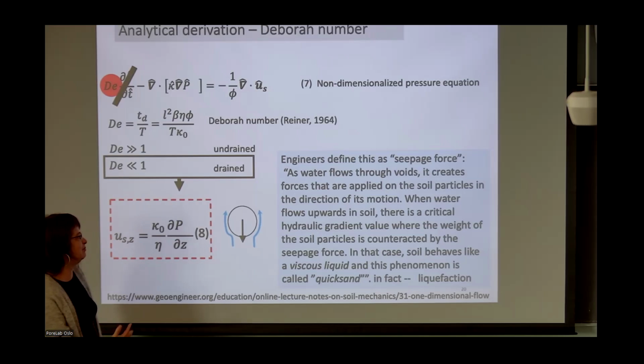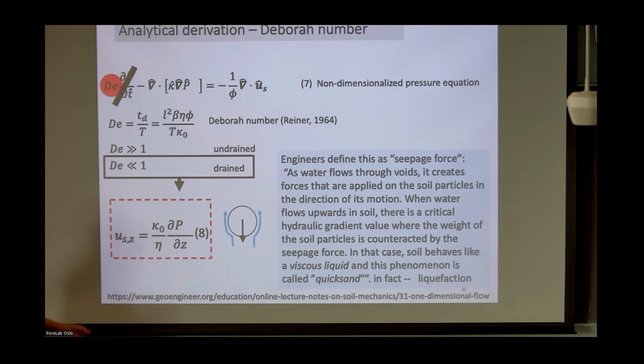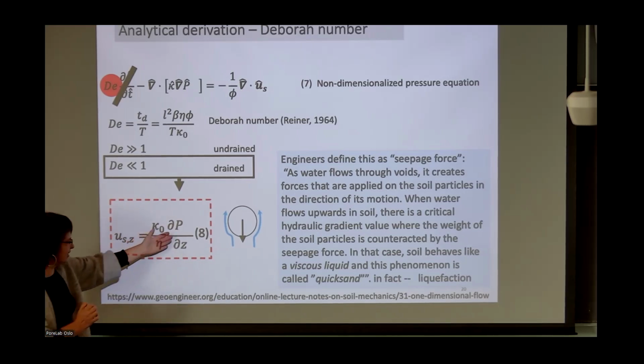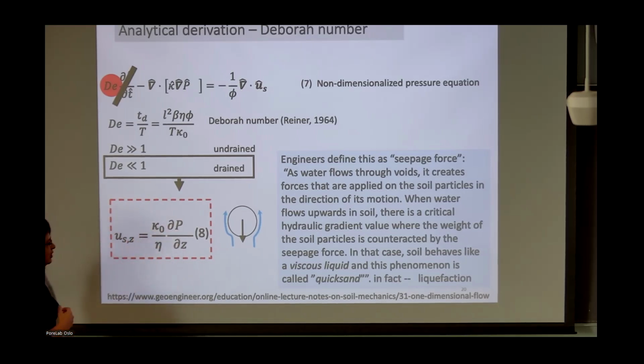And it drags the soil particles. There is a critical hydraulic pressure gradient, which is basically the lithostatic pressure gradient, where the weight of the particles is counteracted by seepage forces. So they hold it up. And this phenomenon leads to this whole granular material behaving as a viscous liquid.